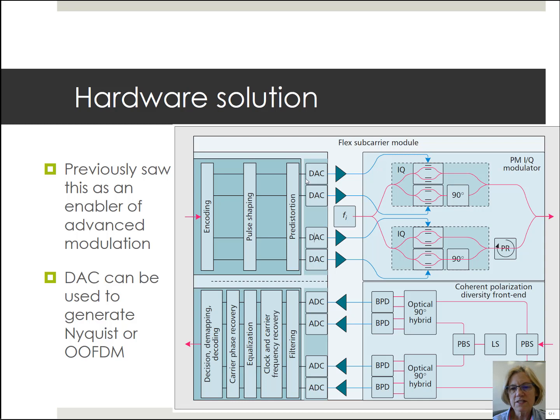So all of this technology readiness that I described comes from trying to achieve other goals, just trying to push bit rate, but it also has brought us to the point of sophistication where we could use the same components to do double work, if you will. So we're going to combine this Nyquist pulse shaping, but also use the IQ modulation in order to do this in both dimensions of this two-dimensional constellation.